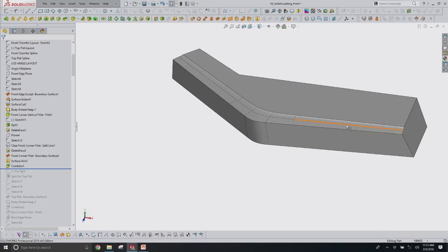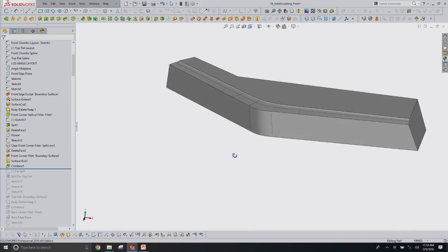And you can see that little white highlight here. If we just had a flat face, we wouldn't get that little highlight there. So if we want to really emphasize character lines on the models, try to think of including a little bit of a kick up, a little bit of a ramp to have the light reflect off that.